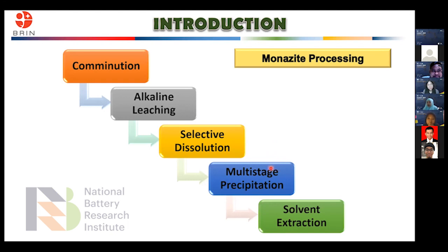All radioactive elements were precipitated when the pH of the REE chloride solution increased to neutral pH, and the REE hydroxide product would be obtained by continuing the precipitation process to pH 8 to 9.